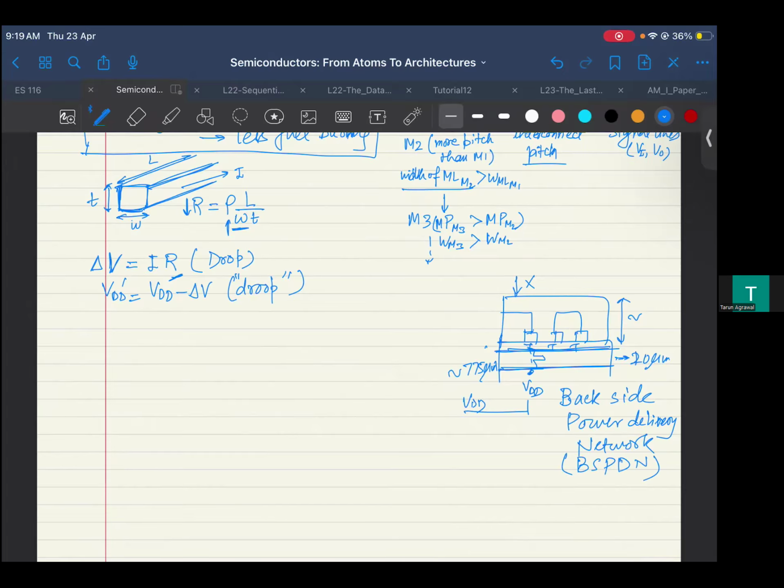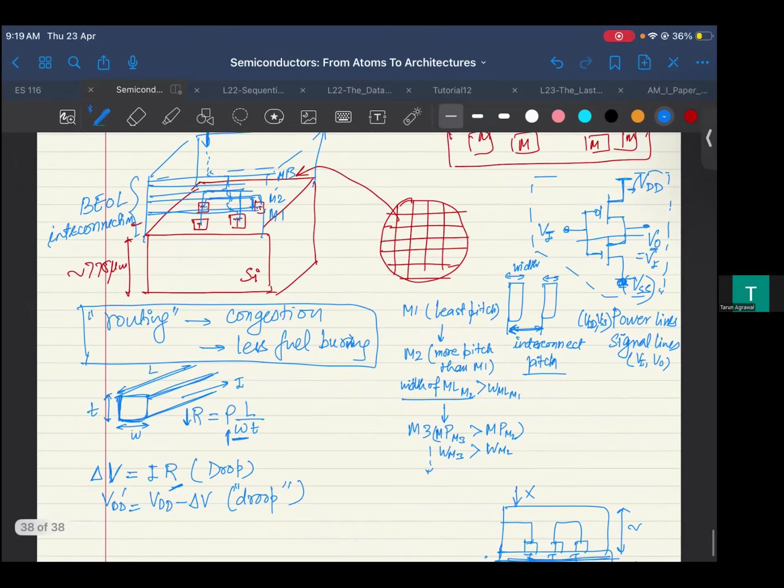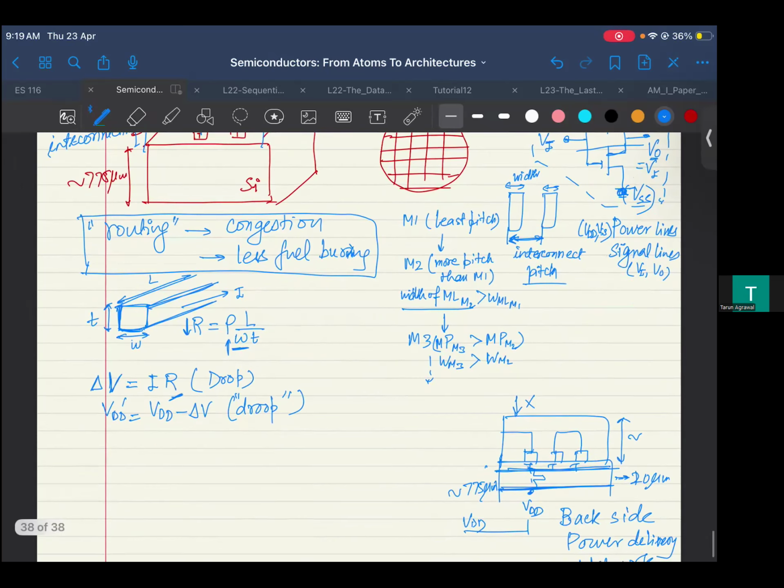One of the very important problems there, and we also work on this problem, is that when we thin down silicon, all of these transistors are generating a lot of heat also, right? Because you know that there are resistances. Whenever there are resistances, there is Joule heating, which is your I squared R losses, right? So this generates heat. We have seen the basic fundamental reason for this heat in the generation-recombination video, what is happening when the electron is going up and down in the semiconductor.